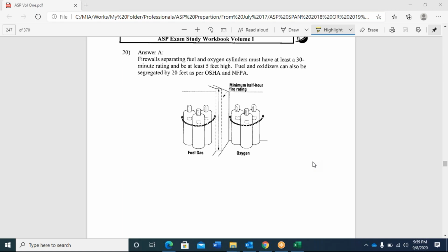The red one is accepted by the civil defense as 1 hour fire rated. The fire doors give at least 2 hours fire rated, and the outer cladding gives 2 hours fire rated also. When you want to increase the fire rating, you install two gypsum boards and put stone fiber or fiberglass in between. In this case, it will give you 2 hours.